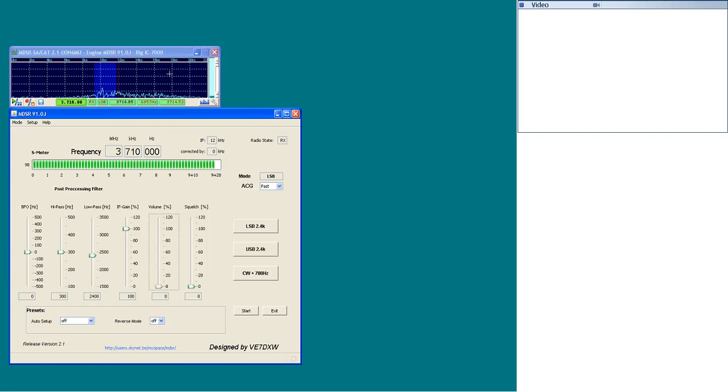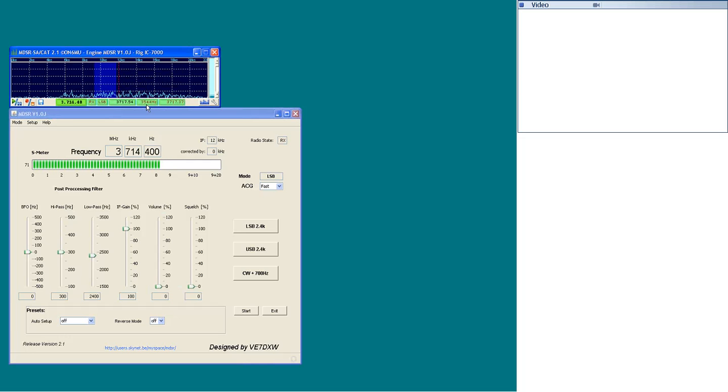In the current cursor frequency window, the real frequency of the cursor position is displayed, and by left-clicking, the VFO in the transceiver is updated. This can be useful to select a carrier and to center it. The delta offset window gives the frequency offset referenced to the VFO frequency from the current cursor position. The dominant frequency display shows the highest peak of the current spectrum. Left-clicking on it will update the VFO in the transceiver.